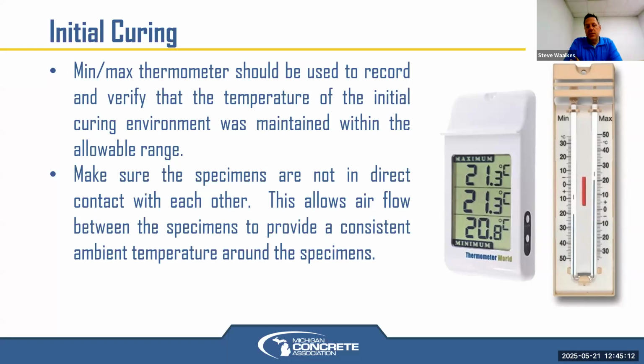So I've heard of technicians taking empty cylinder molds and filling them with cold water, filling up the cooler with cold water from the hose and the tank on the ready mix driver's truck. Or I've heard of some, even in really hot weather, filling some of those empty cylinder molds with ice and water so that the ice will melt and the water itself also will act as a heat sink to pull all that heat that's being generated by those cylinders, and the heat will go into the water.